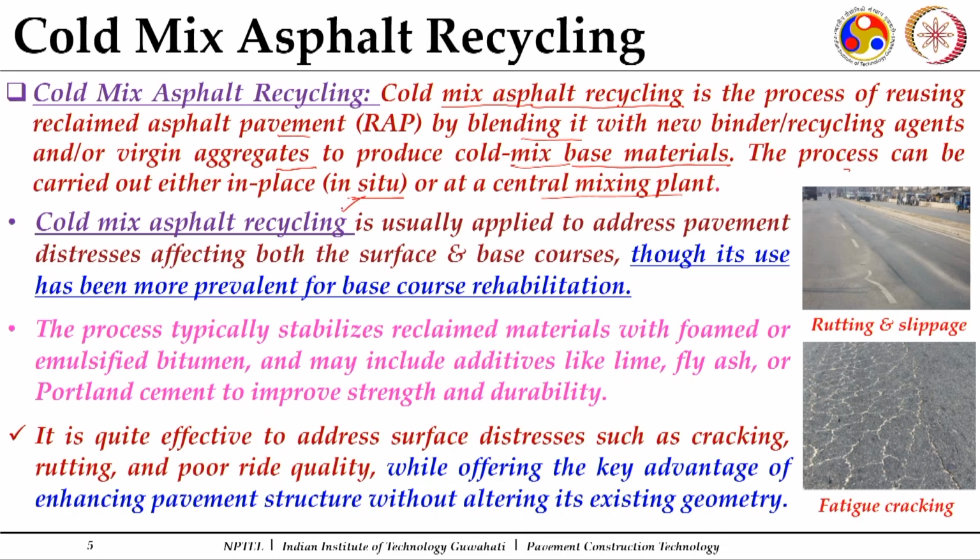First, coming to cold mix asphalt recycling: what kind of distresses can be addressed? The wonderful part is that a significant number of distresses can be addressed with cold mix asphalt recycling. It is usually applied to address pavement distresses affecting both surface and base courses. You can go for a greater depth, specifically the bituminous wearing course, surface course, or the bituminous binder and base courses.